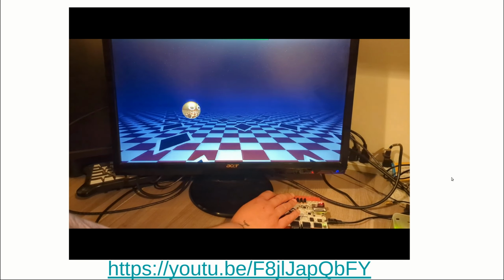It's 1080p, so it's 148.5 megahertz, and in this clock domain, this function is generating VGA timing, the V and H sync. It's counting off X and Y positions, and so that's what's being fed into the pixel rendering. So you say at position XY, and that's one pixel per one of these clock cycles going into this render pixel pipeline, and then out the other end comes the pixel color and the rest of the VGA signals too.